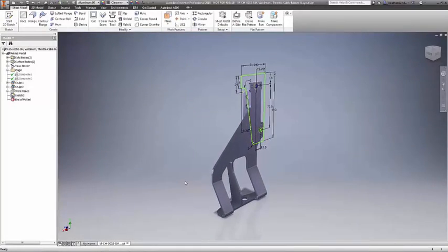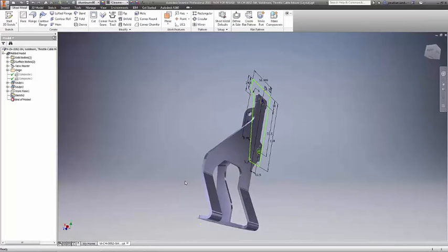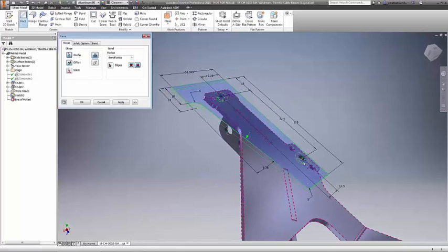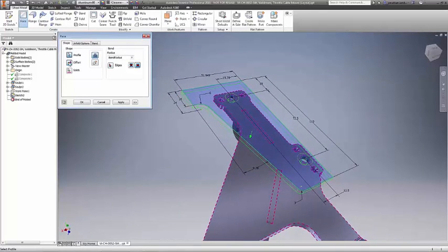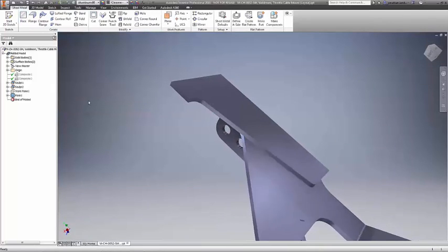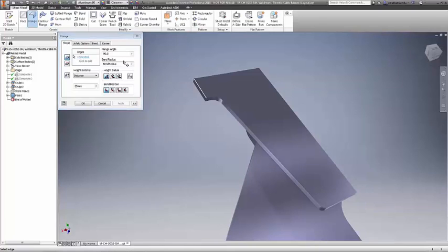Another key enhancement revolves around designing sheet metal parts with multiple bodies, enabling faster engineering times for designs of sheet metal parts that are complex. Now create multiple sections of a sheet metal part, without the sections being continuous, and then connect the sections later. And this workflow supports many of the standard sheet metal operations, including flanges, corners, hems, bends, cuts, folds, rips, and punches.